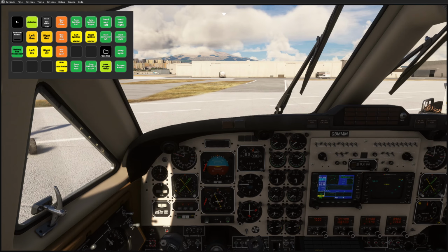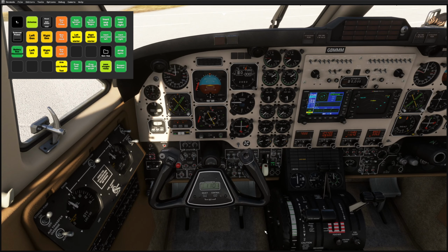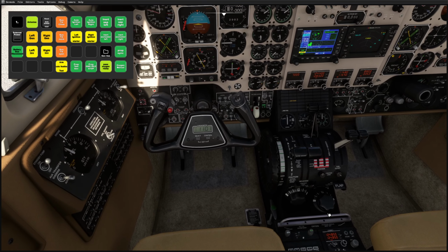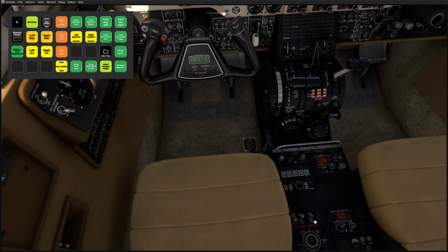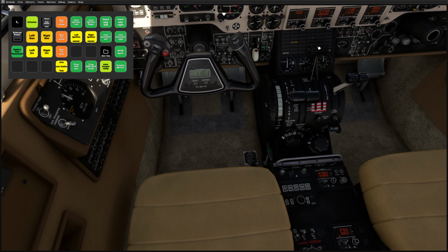So those are the buttons on my yoke. So I'm going to activate that. That's working, and we'll make sure that that is centered. And then it wants me to cycle this, and we're checking for an annunciator on here. So we're going to cycle the electric trim, and there's the annunciator on and off, so that was working.